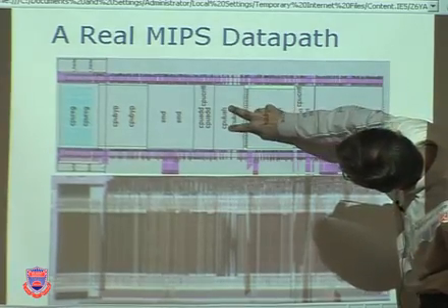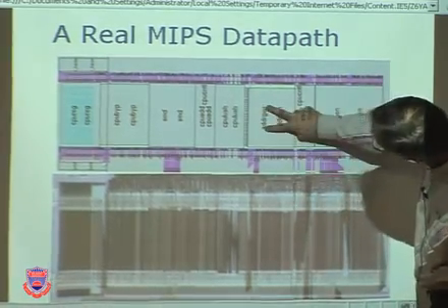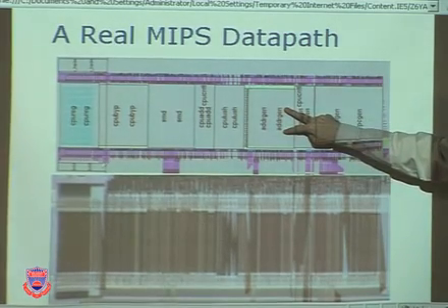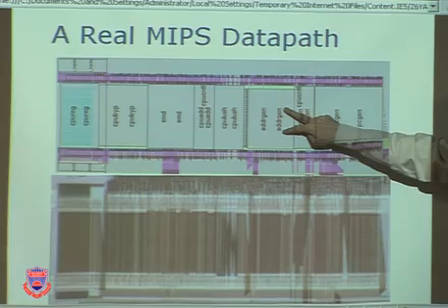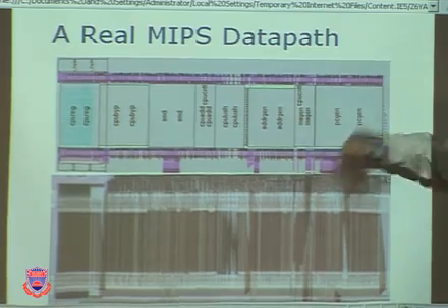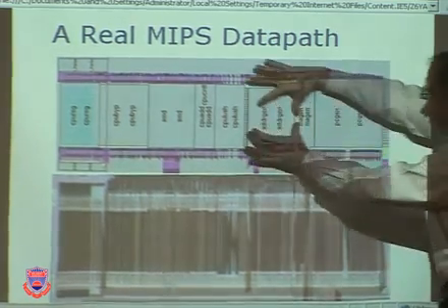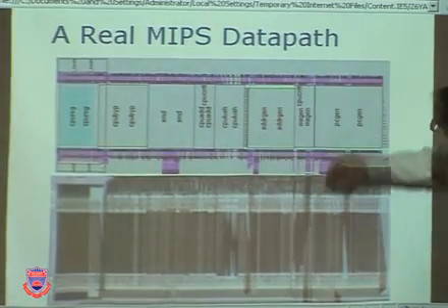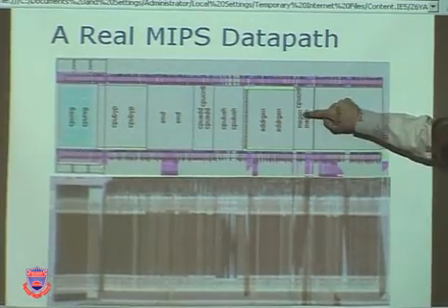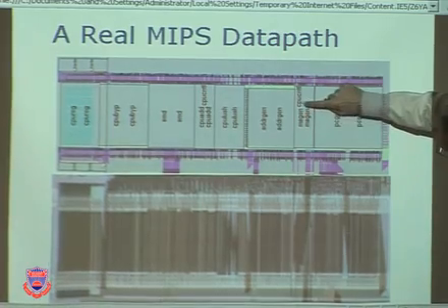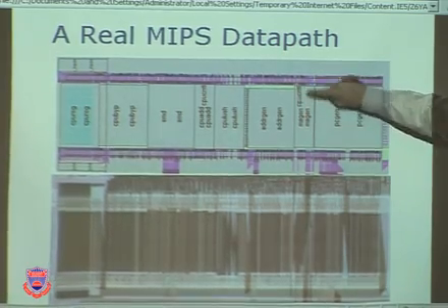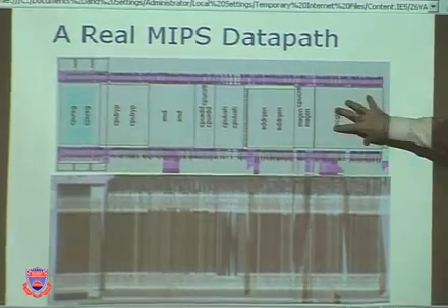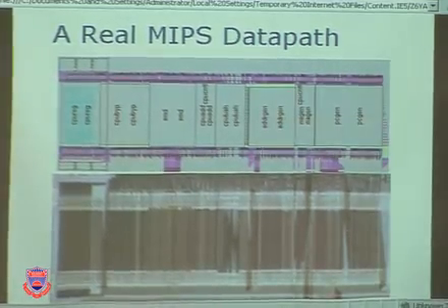CPU lush, it looks like CPU LUSH. Not sure. Add gen, that's address generation. What do you think that might be? Remember what we called instruction fetch unit, generating the next address. There was a bunch of hardware. That's that block right there in order to figure out what the value of the PC should be next, the address generation. Here's MAGen, that stands for memory address generation. And a little here in the corner, CPU control. So there's some CPU control there and some CPU control there. Oh, I'm sorry, this is PC gen. That's the PC generation. So this is some other kind of memory address generation.